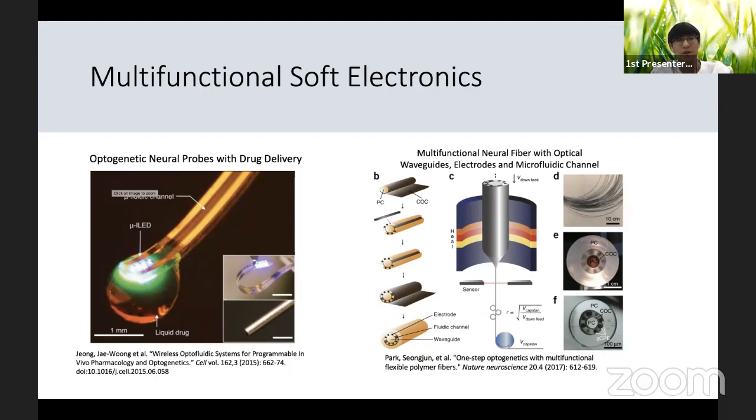Neural fibers enable a mass-producible method for production with easily integratable multifunctionality. A large preform with desired components is created and thermally drawn to create devices that are hundreds of micrometers wide, in contrast to silicon processes, which have stringent and lengthy development procedures. Multifunctional neural probes allow a variety of soft materials, such as polymers and hydrogels, to be used for probes that are mass-producible, multifunctional, and soft.